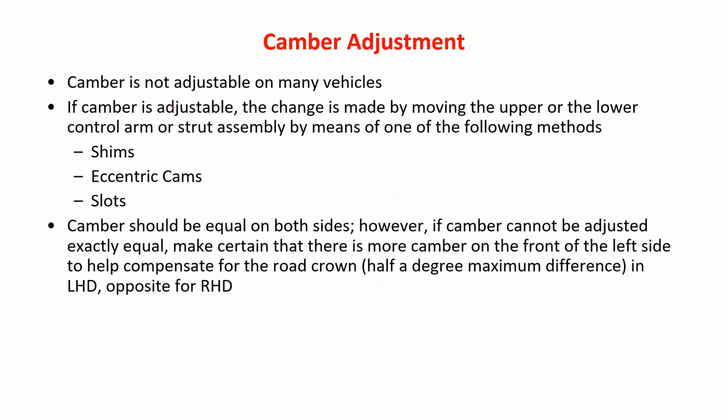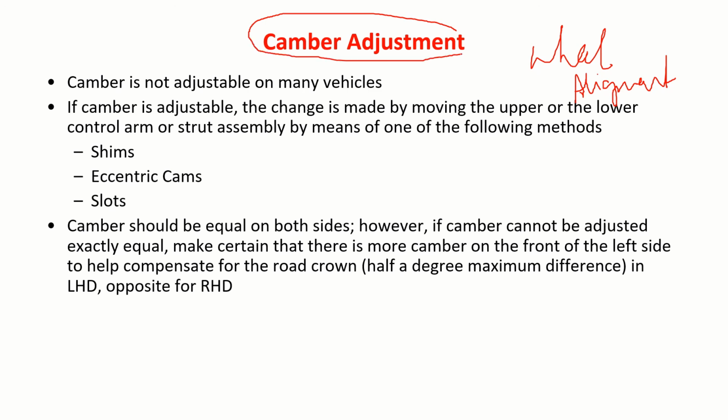So now, in the service station, as I said, because of more wear and tear, camber might change. Quite often we go for wheel alignment of the vehicle. During wheel alignment, the mechanics try to maintain the original camber angle.